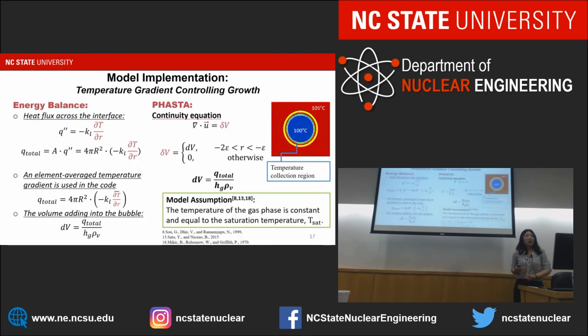And in the next step, instead of using the analytical source term I'm showing in the first step, we're trying to calculate the temperature gradient around each bubble. In the second step, we include the energy equations in the liquid solution. So we're able to obtain the temperature gradient from the temperature field around the bubble.